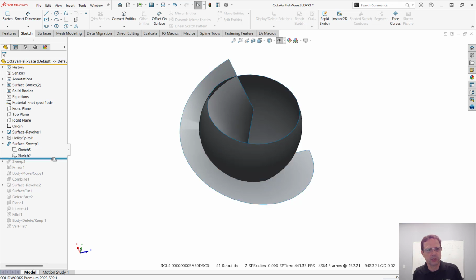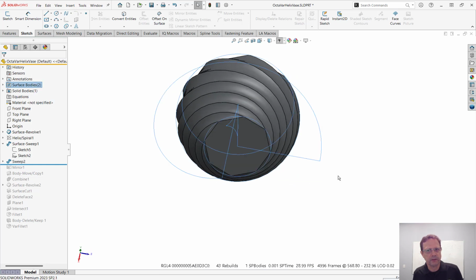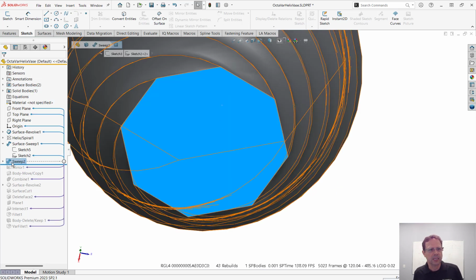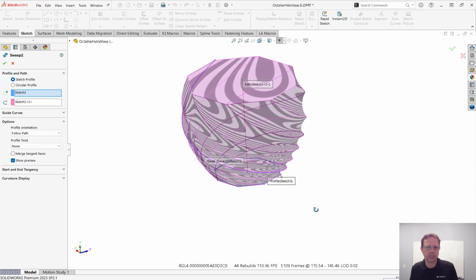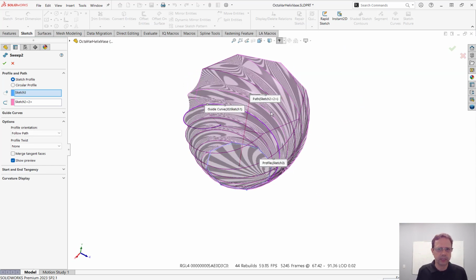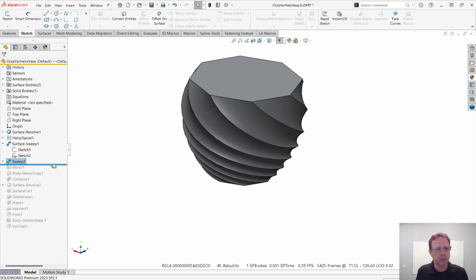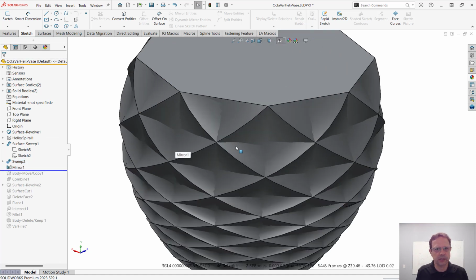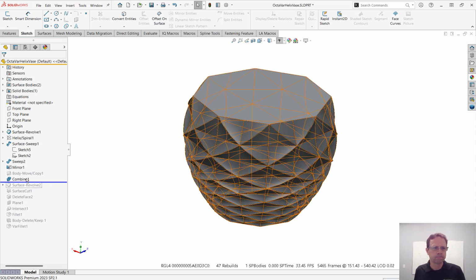Once you have the intersection curve, and this is the cool thing, we can simply use the polygon. Let me hide the surface bodies. So I have this octagon at the bottom that is going on that intersection curve, right? So you can see the result, simply having a polygon that kind of spins around as it moves on the path. So easy solution. Mirroring it, again, all the contestants noticed that this is mirrored. And then I combine the two, so now I have one file only.